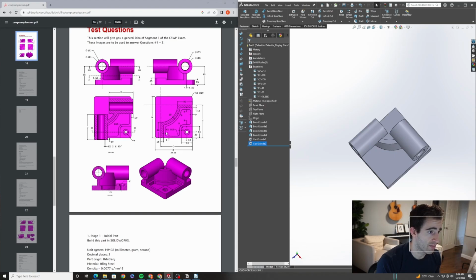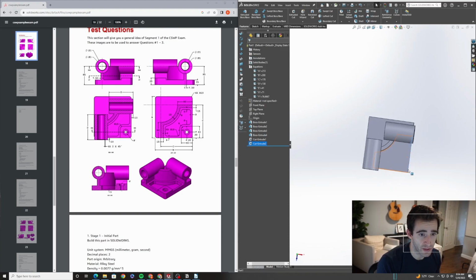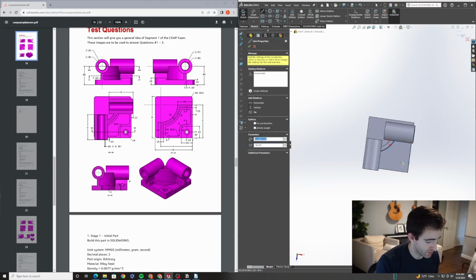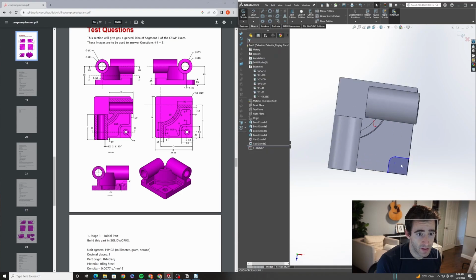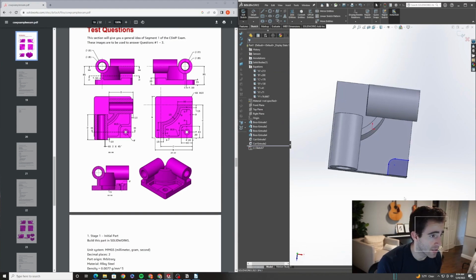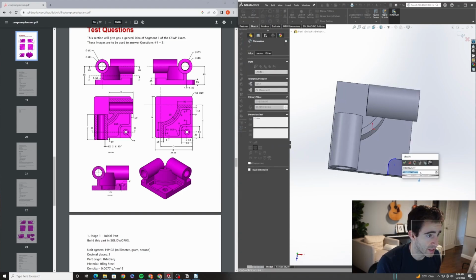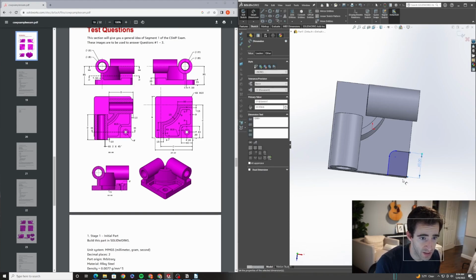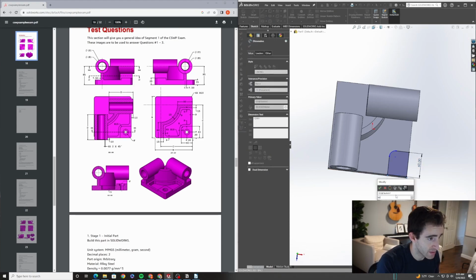Next, I'm going to create this pocket. Well, because that's an offset there. So maybe what I want to do is create this corner feature with the hole. So let's go here, sketch. One trick, I like to use A to create a tangent arc. I want to make sure that this is horizontal and this is vertical. Good. Now, this length is 60. This length is 60.